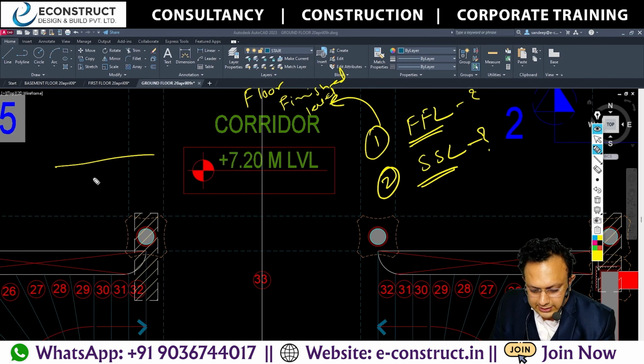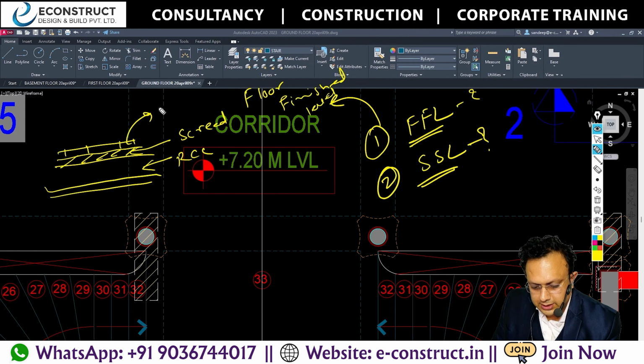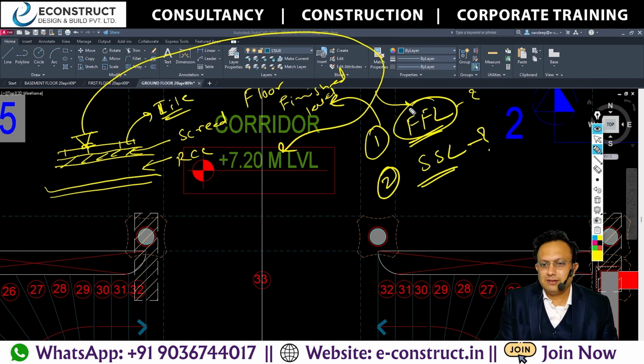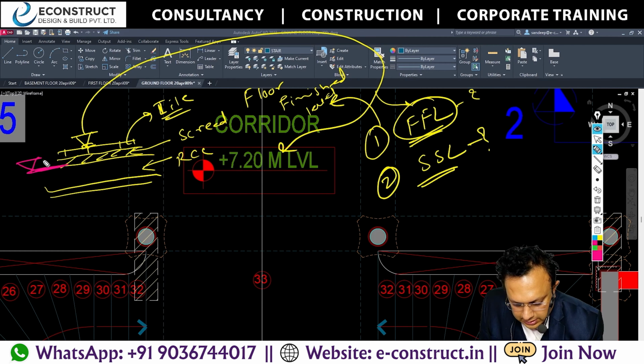Let's say this is the reinforcement in the slab. So there will be the screed here and there will be the tiling here. So this is RCC, this is screed, and this is the tile. So basically you are giving this level over here as a part of the FFL. Understood? So floor finish level is one of the very important levels. And what is SSL? Which is the structural slab level. This is the SSL.